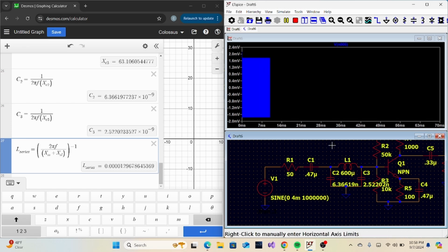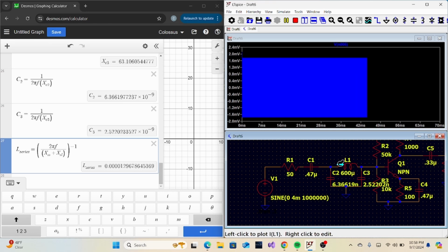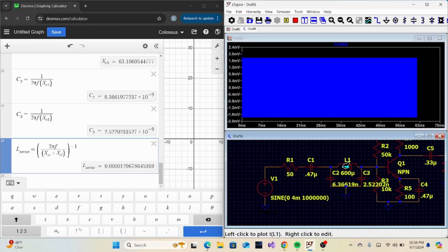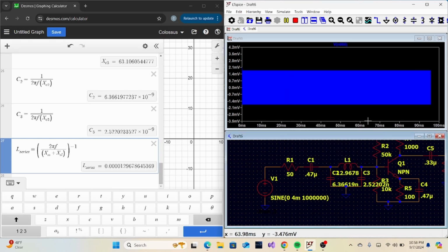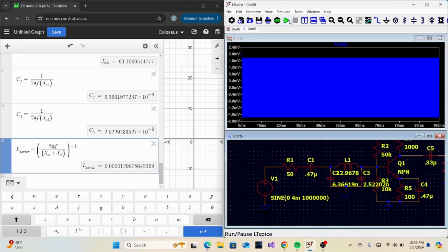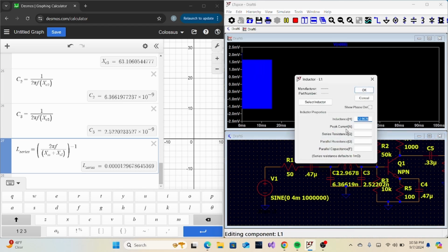It goes below 2 because this impedance is too great at this point. As frequency increases and inductance increases, the impedance increases as well. So we want to have this set to a value that brings us pretty close to 2. That tells us that our match is pretty close. The other thing you can do to see how well the Pi network is working.